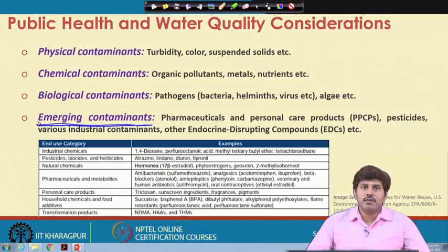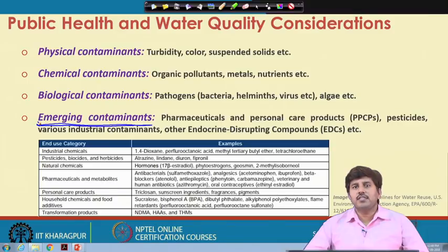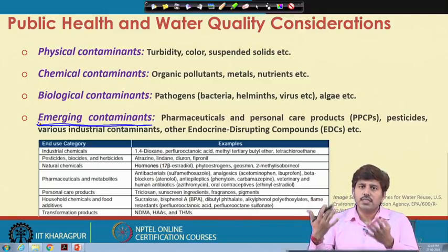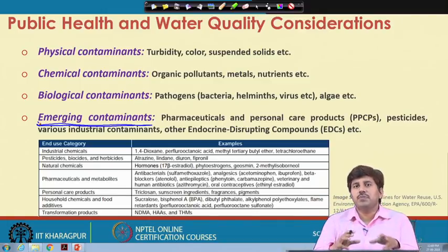So, they are the kind of things that are most crucial, and that is why when we go for reuse quality characterization or reuse quality standard, we must think of the potential risk that these compounds could cause and the chances of these compounds being present based on the point or the source of the wastewater that we are discussing with. So, if our source of wastewater is industrial wastewater, then there are significant chances of some of these being present over there.